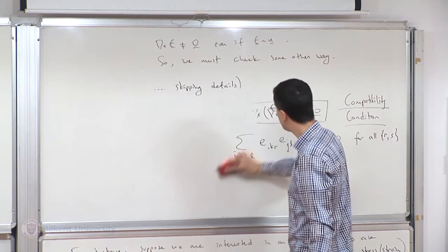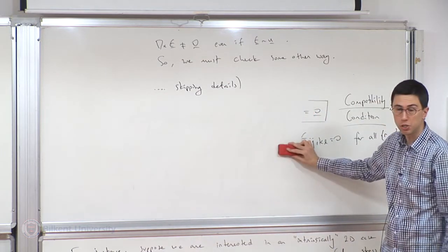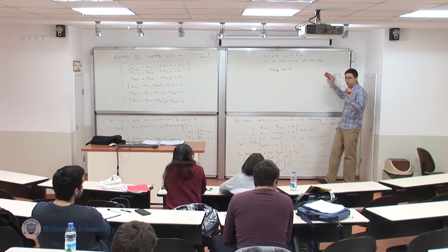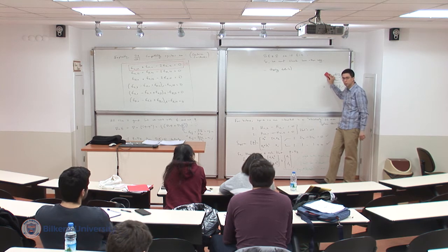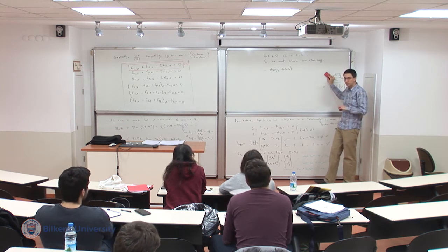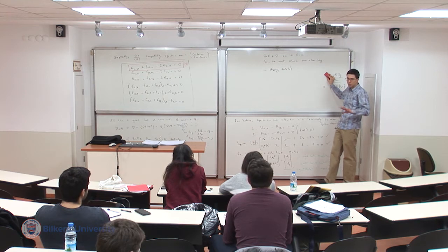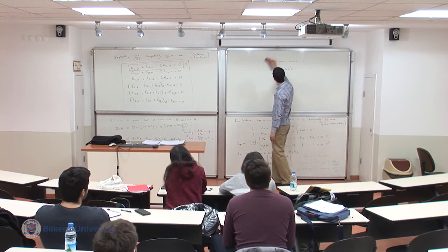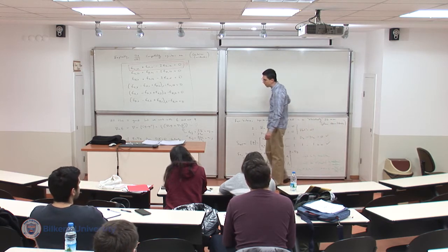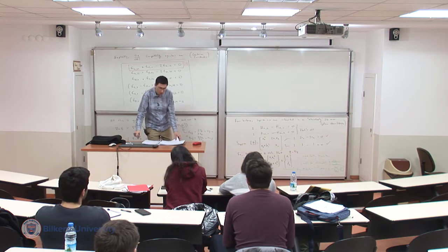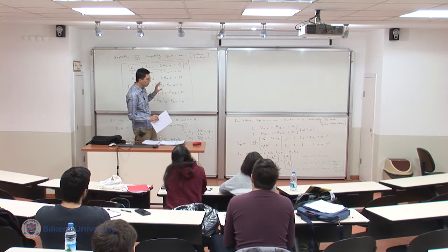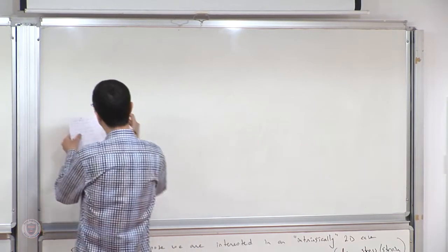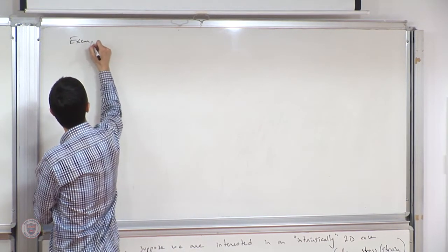But not only is it not sensitive to rigid body translation, it's insensitive to rigid body motion altogether. Small rigid body motion, which means small rotations are also permitted. They would not somehow go into epsilon. Epsilon is entirely insensitive to that. You would see it in H, and we've given an example last time, but you would not see it in epsilon. So eventually when I integrate epsilon components towards a displacement field, I should see some rigid body translation and some possible rotation. And we'll see how we obtain these in this example.